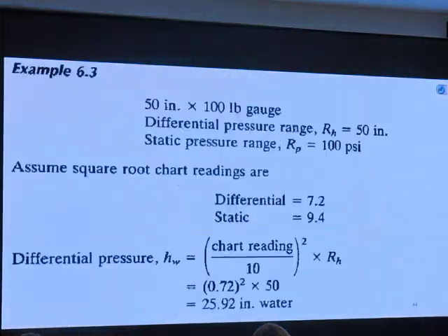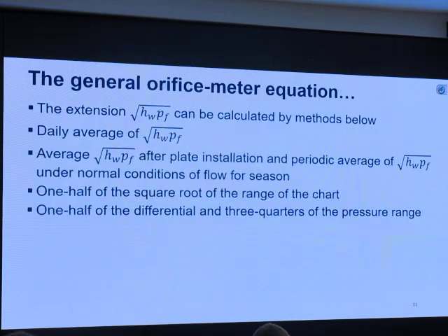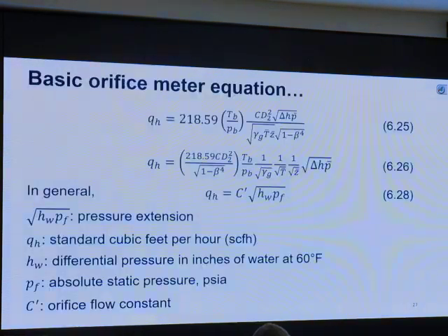What kind of orifice question on the exam may you expect? Number 1, the factors that impact the accuracy of the orifice plate reading. Number 2, you have to be able to convert from standard cubic foot per day to pound mass per day or something. That unit conversion. Number 3, if the numbers are given, you have to be able to use this equation.